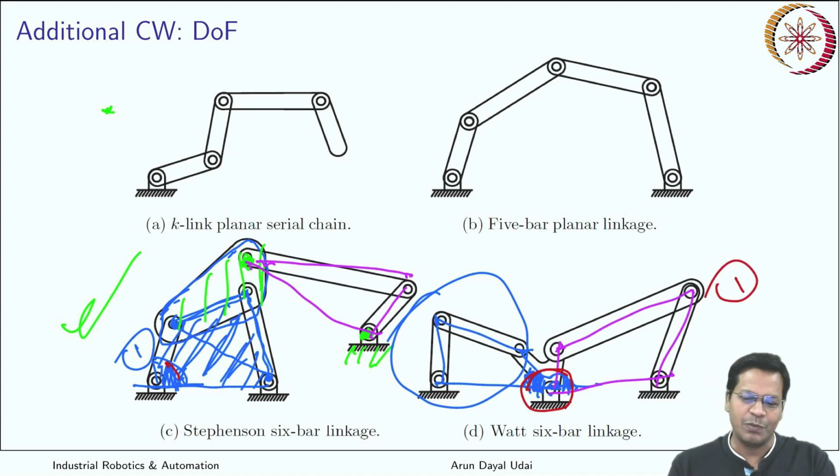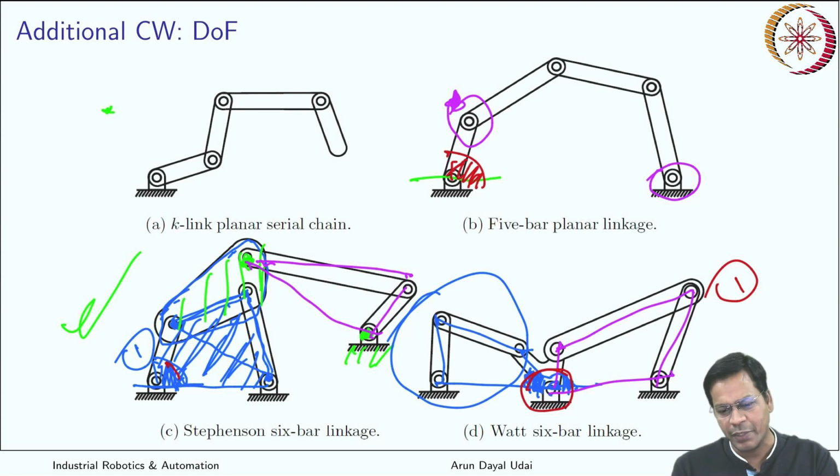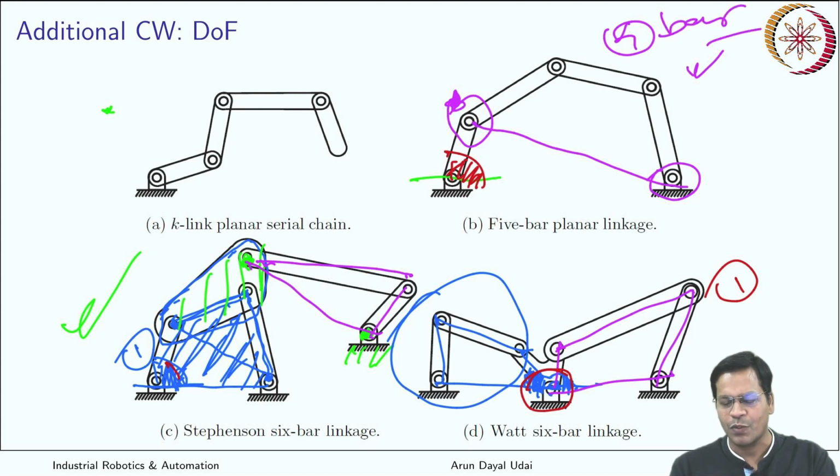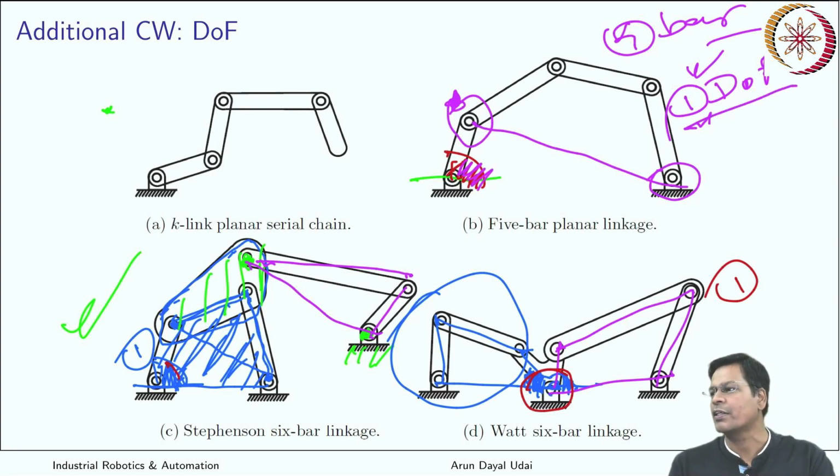Okay, now let us move ahead and do yet another one. So this is a case where I will again go by constraining the system. Let me just freeze one of them. I have frozen this one. So this point is now frozen, this point is now fixed. This one is fixed, this one was already fixed, but still it remains with this 4-bar mechanism. This is a 4-bar mechanism. So this again has 1 degree of freedom remaining. So even after freezing one of them, you are remaining with 1 degree of freedom.